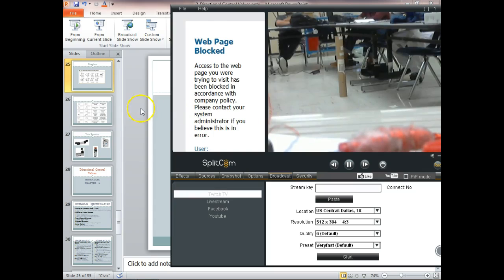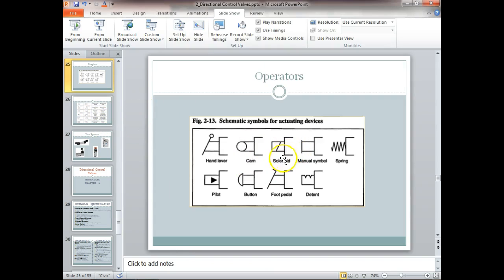Well, since it creates this motion, what can we use that for? We can use that to shift that spool, right? So what's nice about these is they are electrically operated, and I can control electricity precisely. We don't have any solenoid operated valves, but this would be the symbol right here. So what we do is we just take a rectangle and put a slash line through it, and that means it's what? It's a solenoid operated valve.